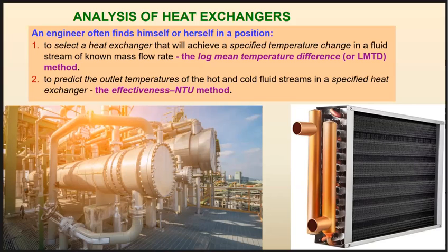It means if you have a higher temperature difference between the cold side and the hot side, you're going to get a better or higher heat transfer rate. So one of the methods of analysis of heat exchanger is looking at that mean temperature difference between the cold side and the hot side, and it's calculated as a log mean temperature difference, or LMTD.